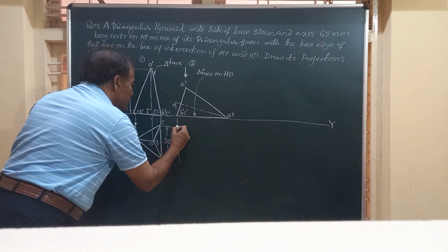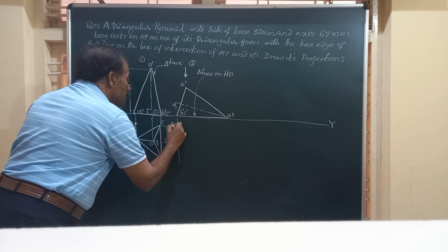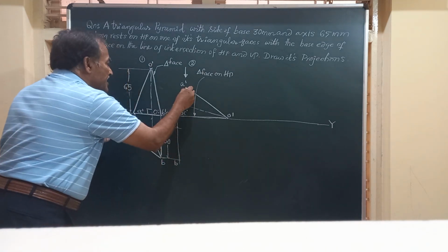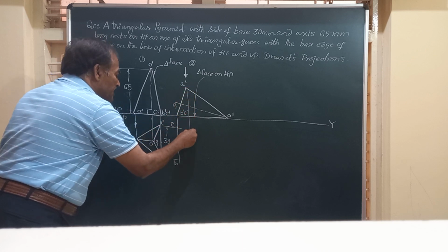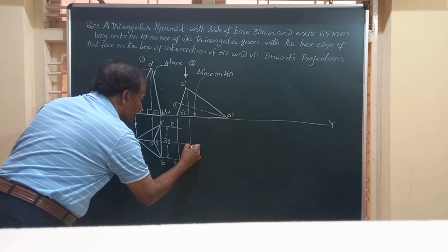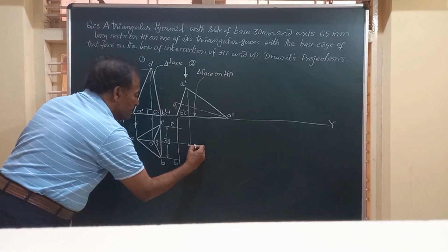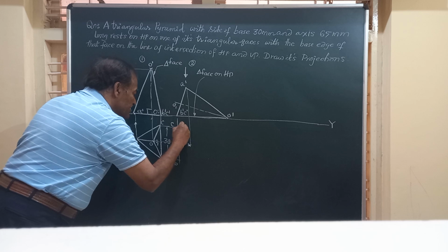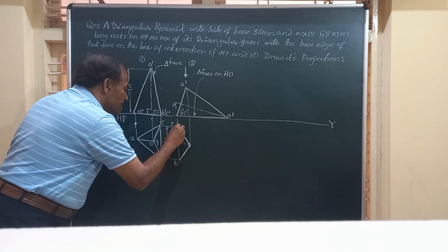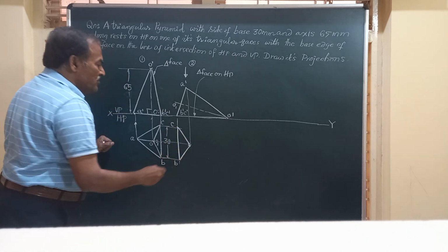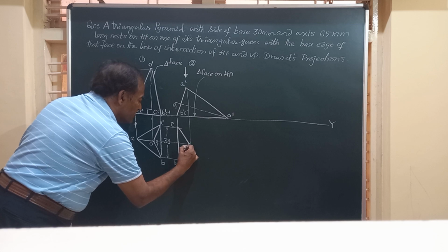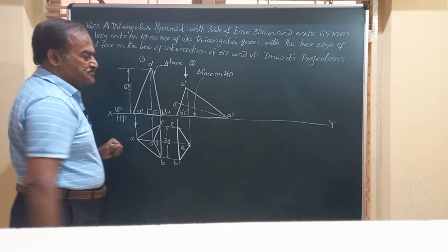You will get point C here, and here you get point B, and finally point A is obtained with the vertical line drawn through this. So I will write a line here, and we obtain these points A, B, C. So this is clearly visible in the top view, and hence friends, we join them by straight lines. So here this is the base of the solid in the top view, A, B, C.